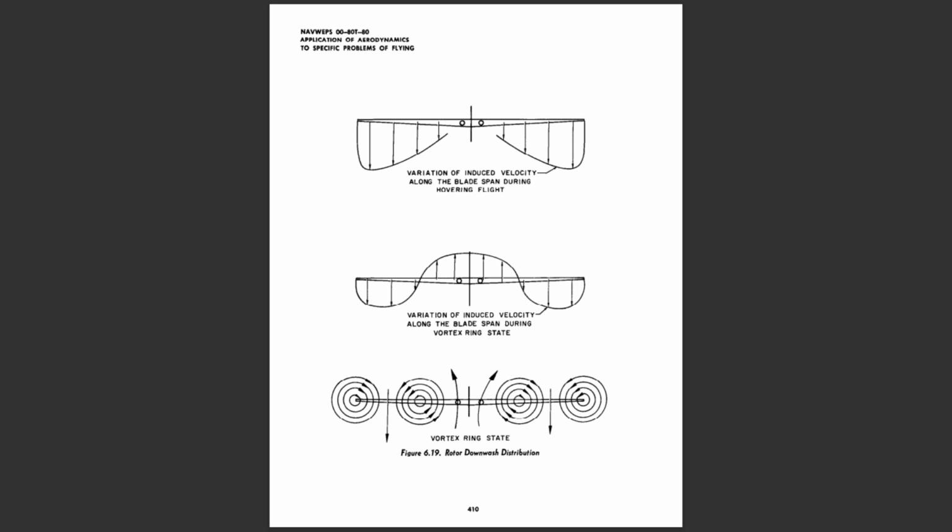As the helicopter descends, a greater upflow through the disc results until eventually the flow is entirely up through the rotor, and the rotor enters autorotation where lower rates of descent can be achieved. Unfortunately, considerable altitude will be lost before the autorotative type of flow is achieved, and a positive recovery technique must be applied to minimize the loss of altitude.